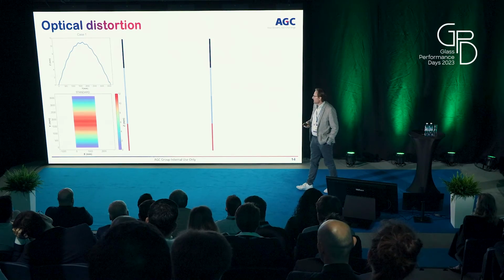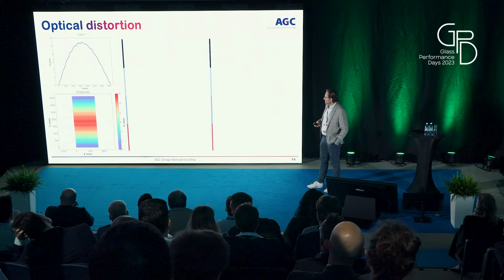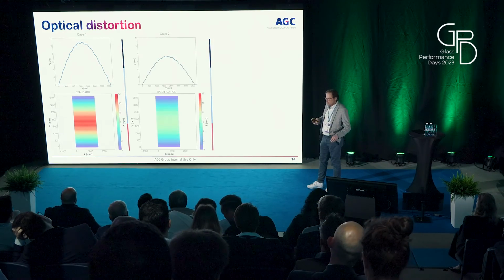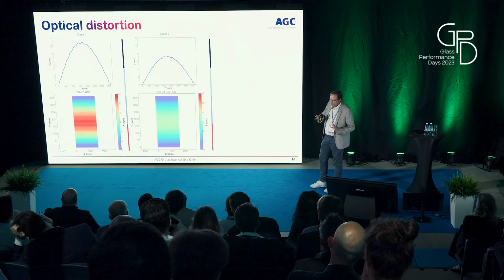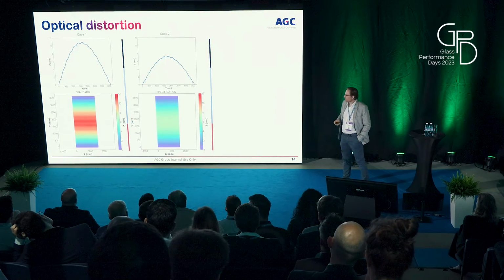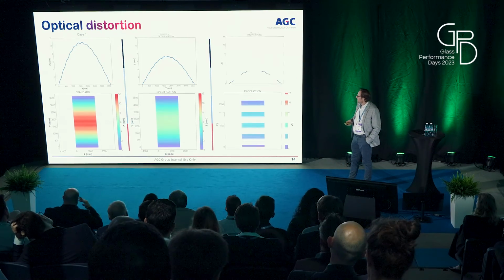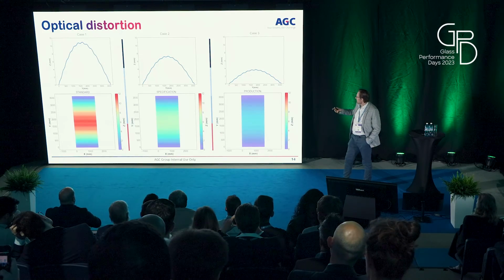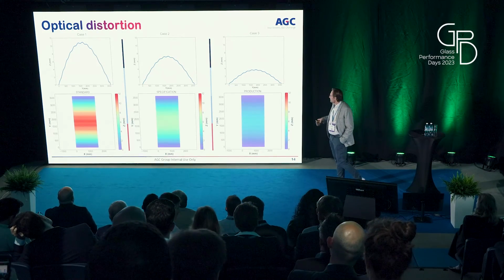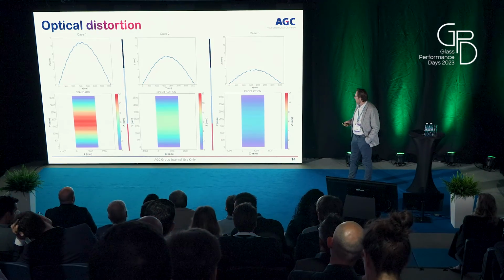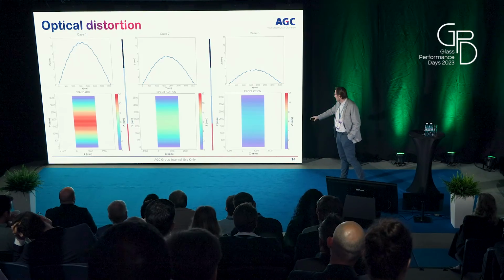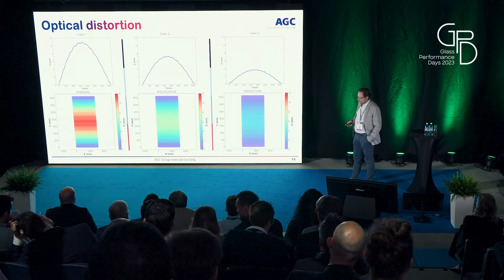It's the highest deflection you get in the center of the glass. Knowing that it's a little bit coming up on the edges, but for the simulation it does not really matter. So we have combined all these values, and you see here the overall distortion is reduced. The overall bow is much clearer and lower, as highlighted in the values.